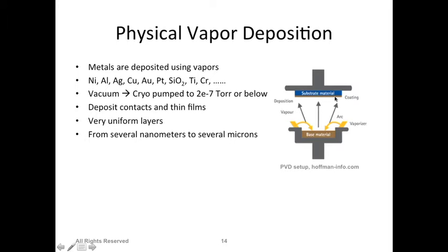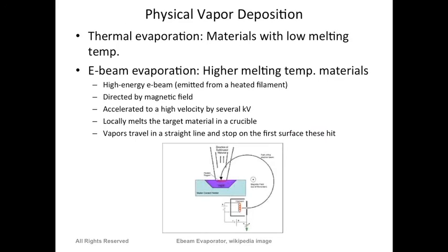So instead of putting only one wafer, you can put a couple of them on the surface because you don't want to waste your material, right? Normally we coat a large area, maybe 10 or 20 substrates depending on how big your sample is, and deposit all of them together in one run. The same applies to E-beam evaporation, but the difference is that you can now achieve high temperatures.